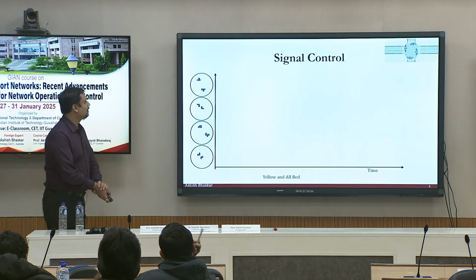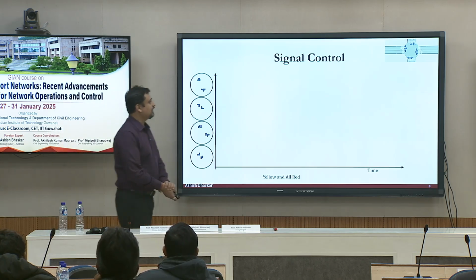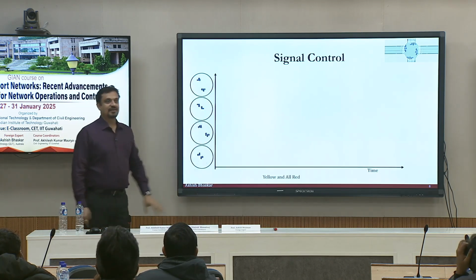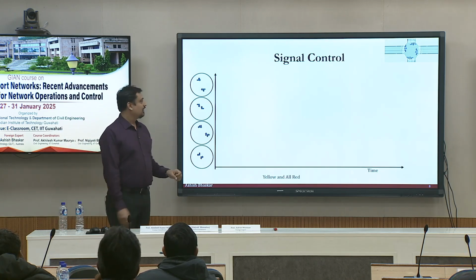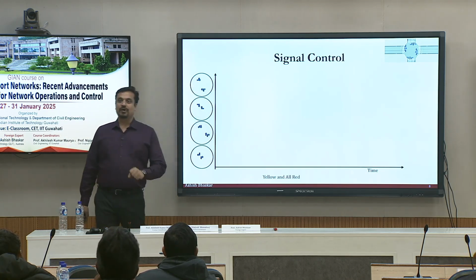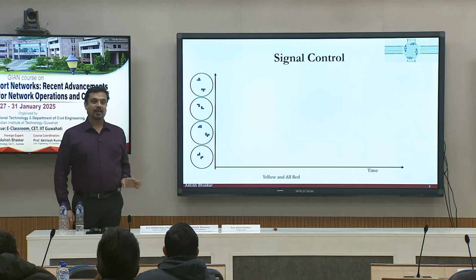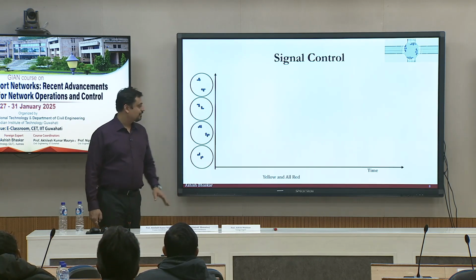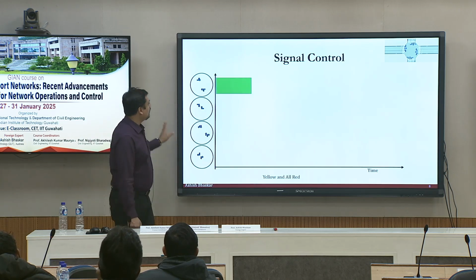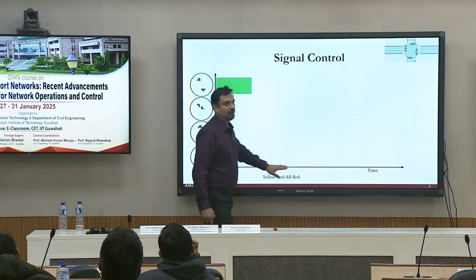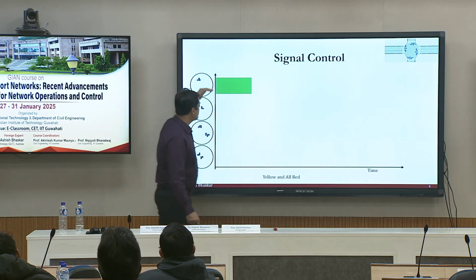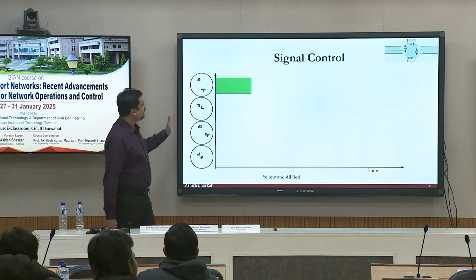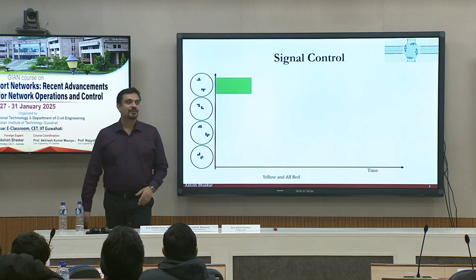So let's have a look. Let's say for this intersection, I have defined my 4 phases. So first thing I have done is, these are the groups I'm going to allow at any given time together. I can allow them. And I've defined the sequence also, for instance. Say I'm going to give a green to this approach. So x-axis is the time here now. And y-axis is just an order. That's all. It's not space. I'm going to give a green for that much time to this approach.